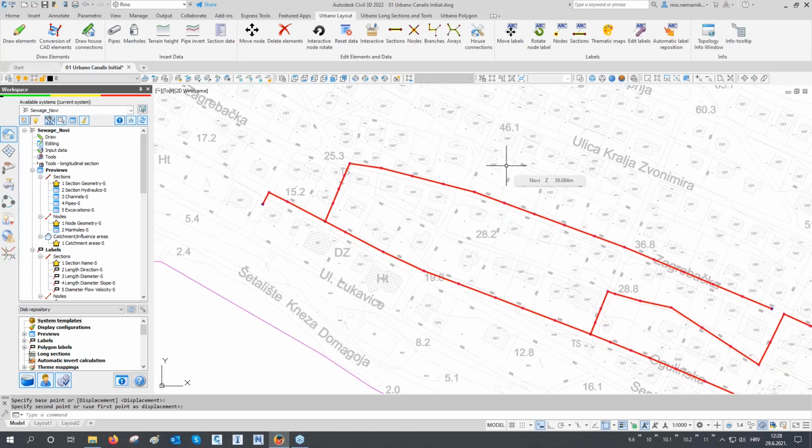I will show this tomorrow, but do not use AutoCAD copy, do not use AutoCAD move, do not use AutoCAD delete, do not use AutoCAD rotate, do not use AutoCAD scale, because with each of these functions you will just be moving something graphically, and then the drawing, this DWG file, will not be in sync with the internal model, with the internal database.